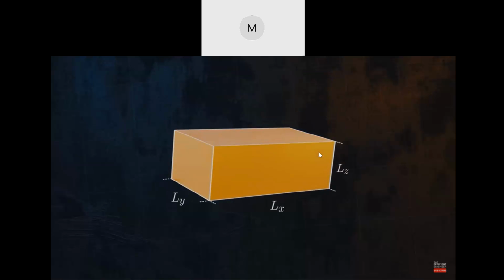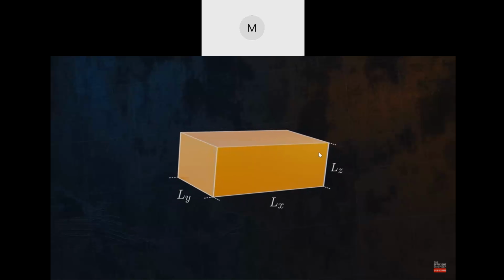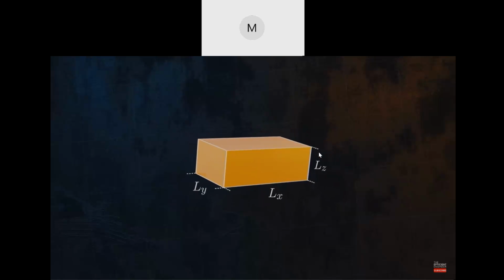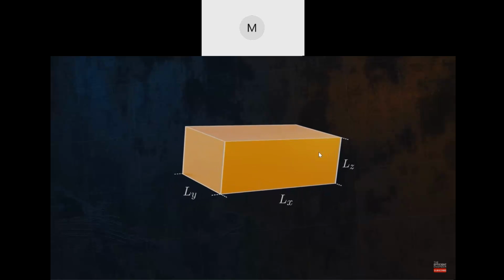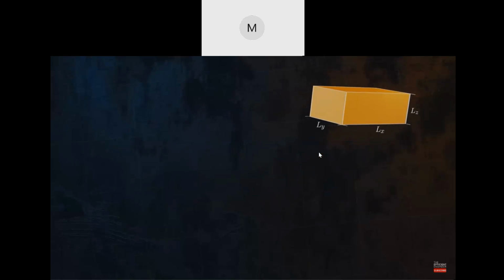There is one last case I would like to mention, which is materials with a Poisson's ratio of 0.5, the maximum value in the theoretical range we discussed earlier in the video. Let's return to our cuboid to introduce the concept of volumetric strain. Volumetric strain is a measure of the change in volume of an object under load. I'm sure it will come as no surprise that it is closely linked to Poisson's ratio. We can calculate the volumetric strain by summing the strains in all three directions.